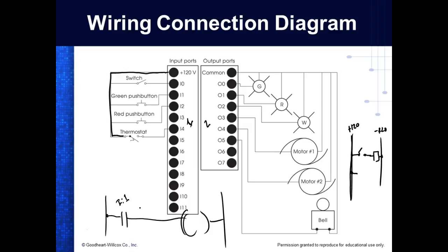Yeah, make sure you address it right. And don't move the modules, because when you write your program, you specify an address of an input bit, right? You understand? When you go in there and shift it around, none of your programs are going to run anymore. It's going to say burp.